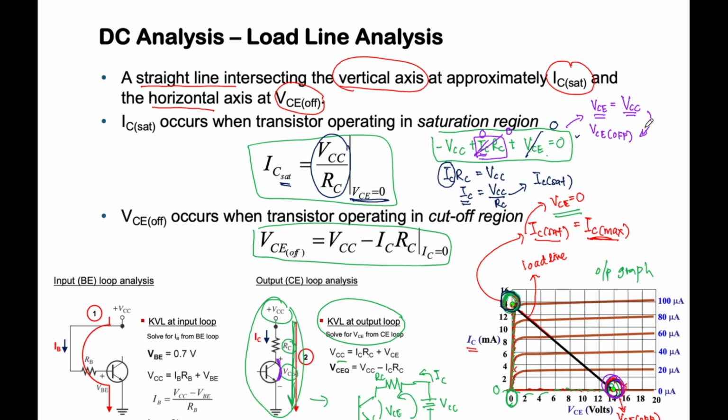Okay, because of why? Because the value of the VCE here will be same as the value of the VCC, meaning that your VCE will not affect anything. It will take straight away the value of VCC. It does not work at all. It will not have a voltage drop or any voltage difference. So it is exactly the amount of your VCC, and during that particular time we said our VCE is equal to off. Okay, and this is only true if your IC is equal to 0.